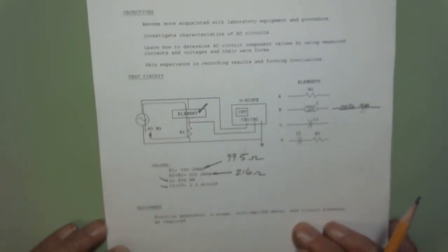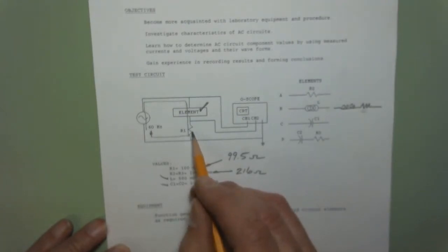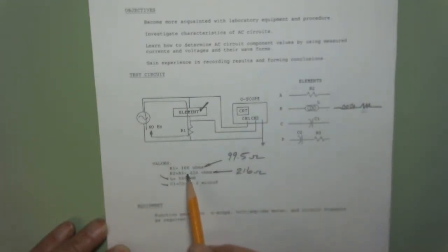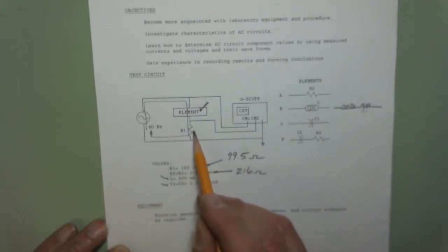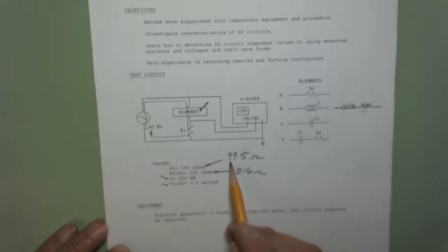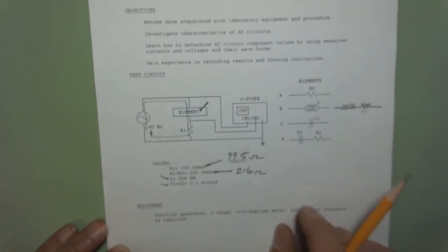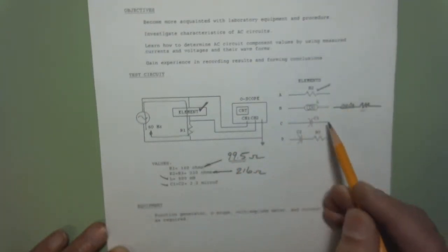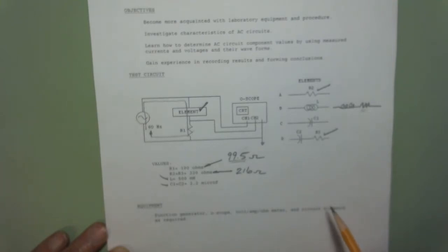One of the things that will help us is having this sampling resistor down here, so we'll be able to figure out what the current is quite easily. When I set up this experiment, I measured this resistor carefully, and while I wanted 100 ohms, I only got 99.5, so that's not too bad. So in my calculations, you'll see me dividing by 99.5. That's where that came from. And then this resistor that we tack on to the capacitor, R2 or R3, I wanted 220 ohms, but I only got 216, and that's okay too.